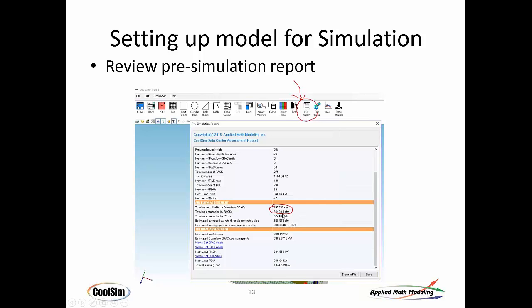Now remember, the rack's flow rate is proportionate to its load at a ratio of about 156 CFM per kW at sea level on a 20-degree delta T across the rack. So what's going on, I suspect, in this case, I do know this case because I worked on it, the room is not yet fully loaded. 245 is the full capacity of the cooling units, and the racks only need 84. So normally that would run and just loop back. In other words, the air coming out of the cooling units would just cycle back to itself.